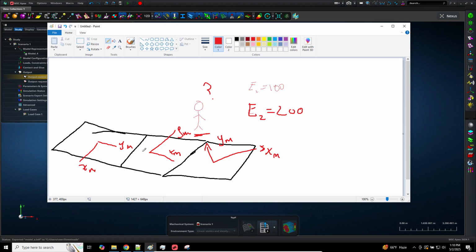It's important for you to know this, because if you don't know this, you're going to incorrectly define your composite laminate. Now, it's the Y axis of the material coordinate system that defines the so-called 0-degree direction. This is a problem because if each material coordinate system is different, guess what? All your 0-degree directions are going to be completely wrong.